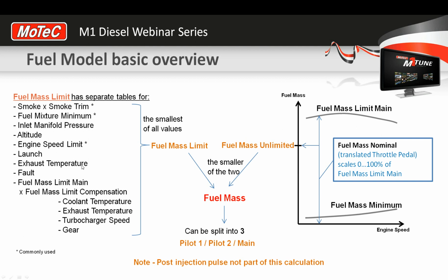Unlike a performance turbo petrol engine, where if it's running 0.80 lambda at 3 bar of boost and we start creeping fuel out of it, it'll make more power and the EGT will go up, which is not what you'd call a safety strategy. But on a diesel, removing fuel is a safe thing to do. It takes power away, it takes temperature away, and there's very little downside.